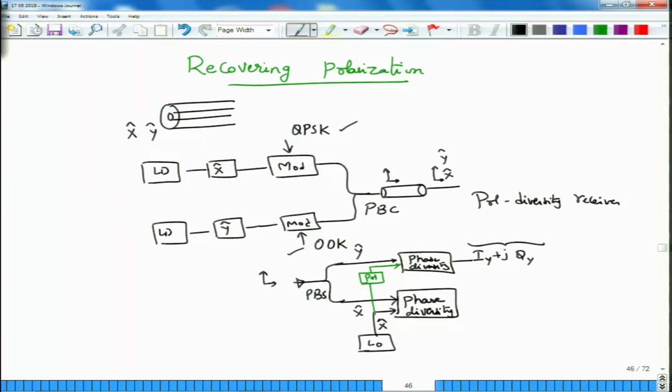JQY being the baseband complex sample that I am going to get, because what I would actually do would be to put an analog to digital converter here which would be running at the sample rate, so that I can actually generate the in phase component and the quadrature component at any given sampling time, and then essentially obtain one complex sample for every symbol that I have been transmitting. Okay. So, once these are the samples, these are actually discrete signals or digital signals. So, please keep that in mind.